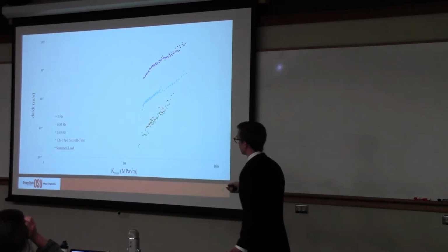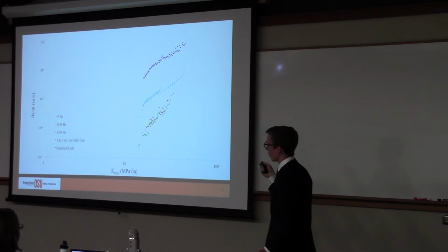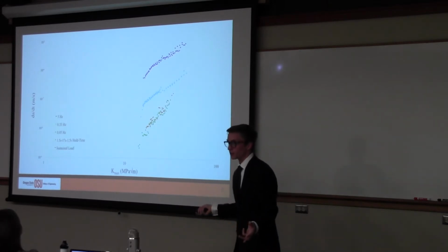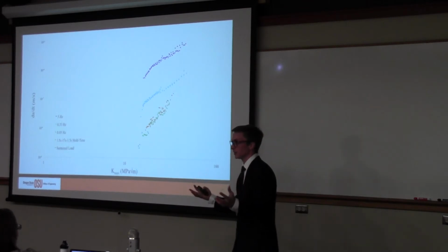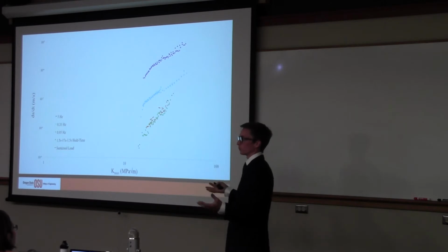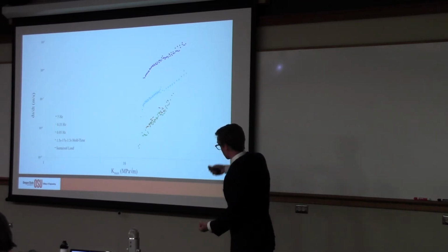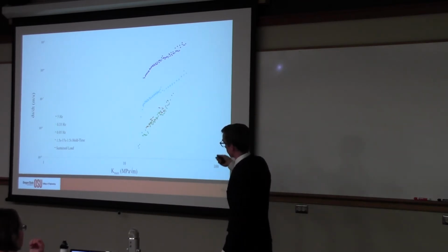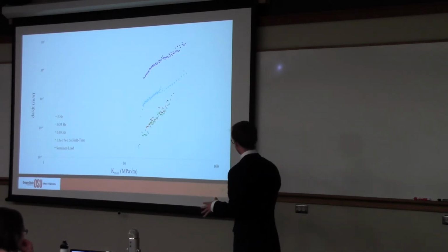Okay? And the thing is, this tells us something really, really important, that the sustained load crack growth rate overlaps with the low frequency. And what does that mean? It means there's no creep fatigue interaction. Pure creep crack growth, which you could say, more the proper nomenclature, is the pure sustained load crack growth. It overlaps with this fatigue waveform that we've got, either the whole time or the triangle waveform. So that's important. That's an important finding.